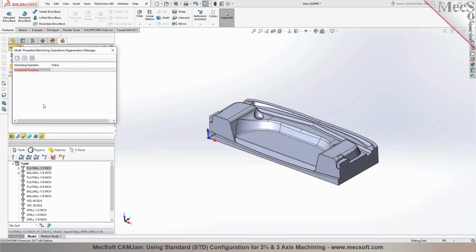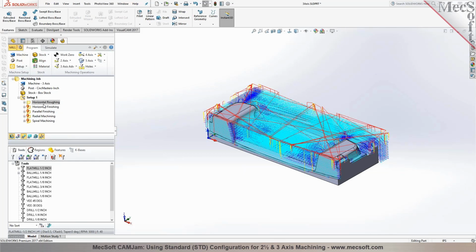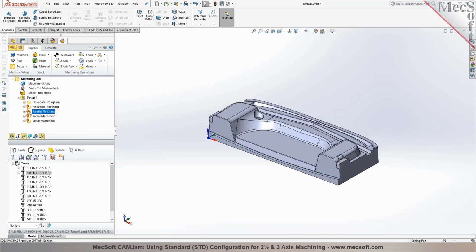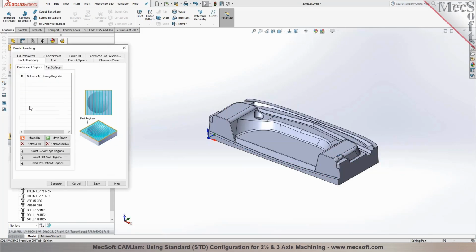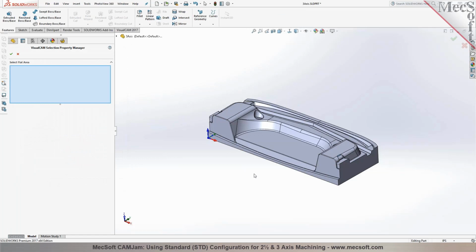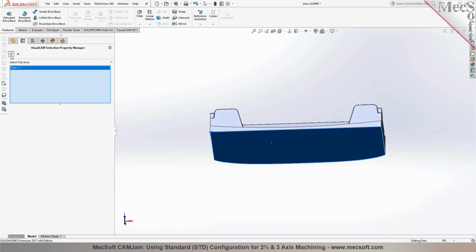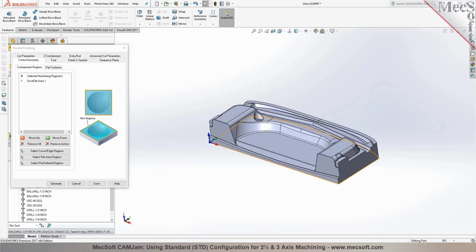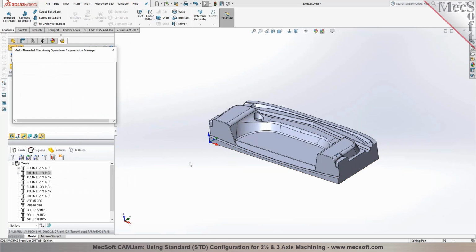The toolpath is being computed. What it's loading from the knowledge base is your cutting conditions, like your step overs, your step downs, your tool, your feeds and speeds, all the cutting conditions. But the geometry could be different in here. So you could take advantage of your knowledge base to program a wide range of parts, like a family of parts, or parts that are similar, or parts that require the same workflow. You can apply those knowledge bases to it.